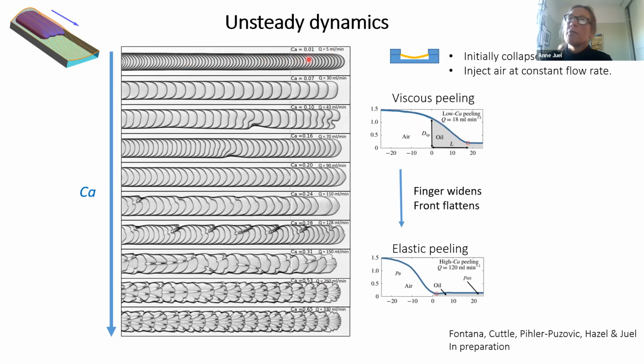So you get fingers a bit similar to that, because you have a lot of fluid in front of your fingertip. As you increase the capillary number, there's less and less fluid in front of your fingertip, and you end up in a situation where you have a competition between elastic forces and surface tension forces, and viscous forces become very minor in setting this reopening of the channel.